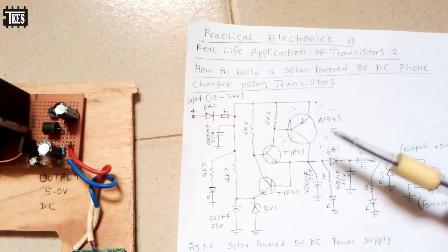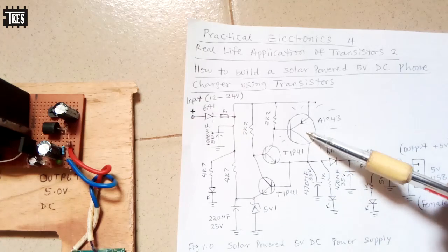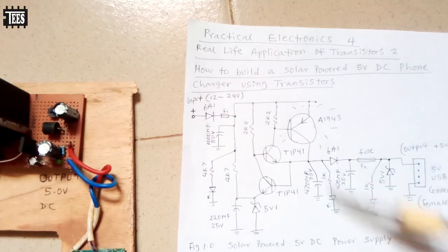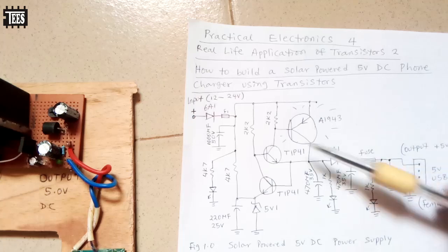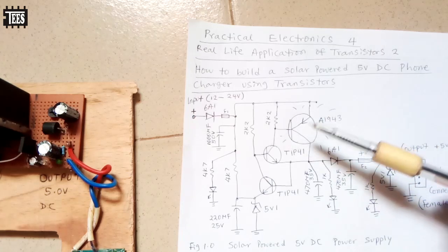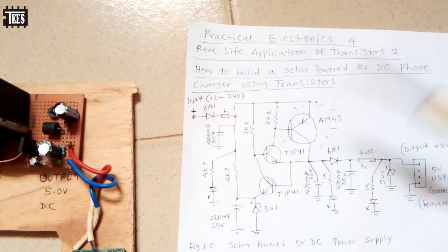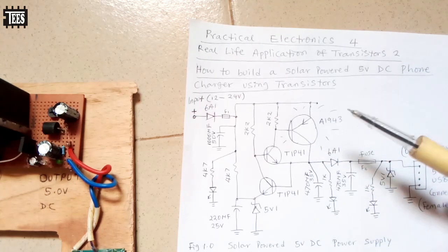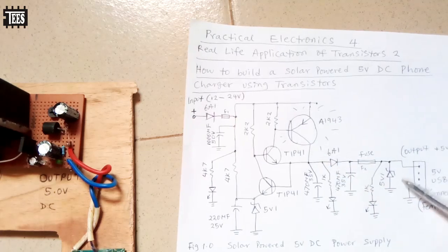So this transistor that you see here, the current rating. Now when you are designing something like this, you will need your output current that you need. Whatever current you need, make sure your power transistor's current rating is twice what you need, or 3 times, or 4 times your required current. For example, if you need the output 5 amps, make sure your transistor is more than 10 amps, 15 amps, 20 amps. Make sure this one is far higher than what you need.